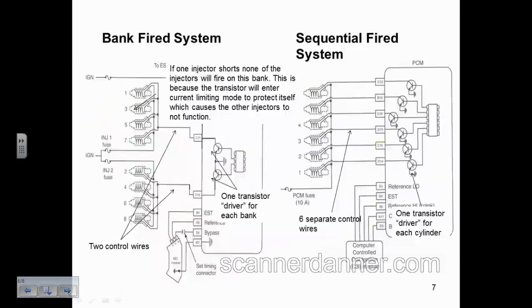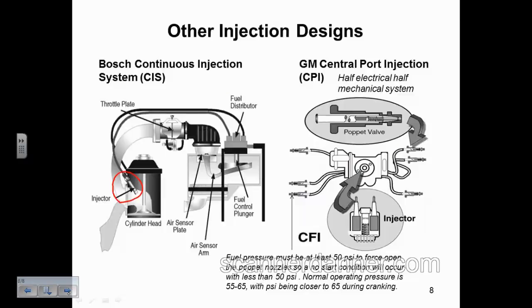Come down here to this, and let's talk about that for a second. So if it's spraying fuel all the time, what affected the amount that it was spraying was pressure. If we vary the pressure to that injector, we vary the flow rate of that injector.